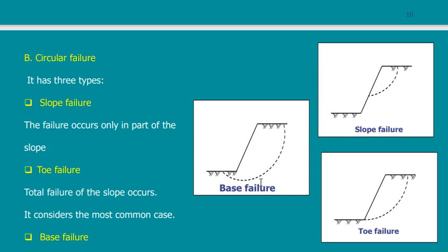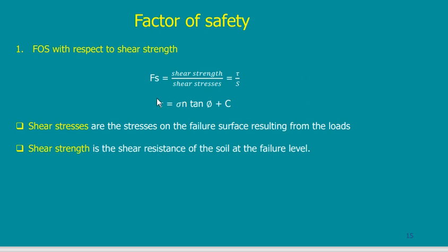And if somebody else comes and tries to push me with the other person, and they both push me with a force of 5, he can still carry these double forces, which is 5 and 5 to be 10. So this is my factor of safety. Factor of safety means the force that is keeping me in place compared to the force that wants to let me fall down.